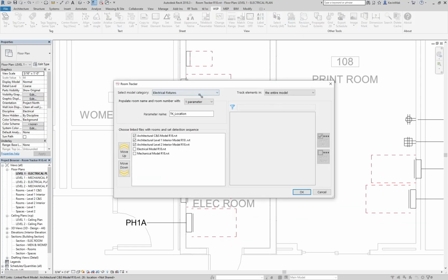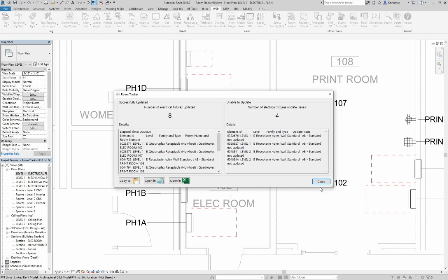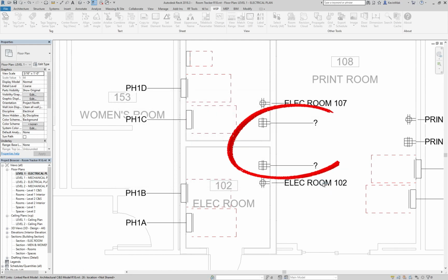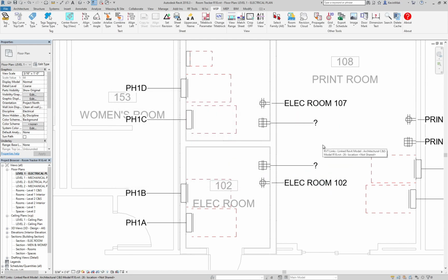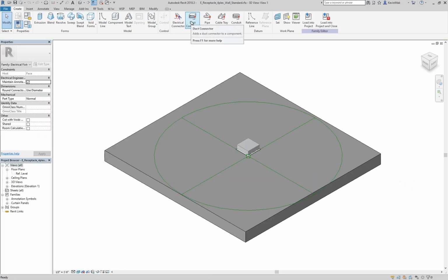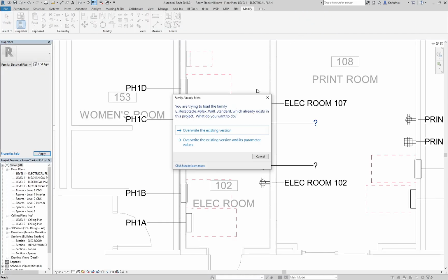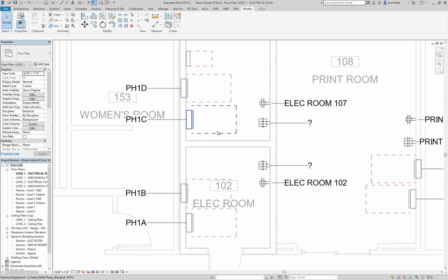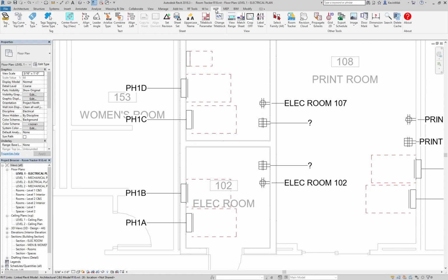The architectural walls can have multiple layers. When placing wall-mount devices and fixtures on the wall, the device or fixture could mount to the inner layers easily. To address this common mistake, turn on the room calculation point in the family. The room calculation point is a feature in Revit that allows the user to schedule equipment per room more efficiently. When the room calculation point is turned on, a green dot appears, indicating that the room is aware of the fixture. Load the family back to the project. This ensures that the room accurately recognizes the fixture.